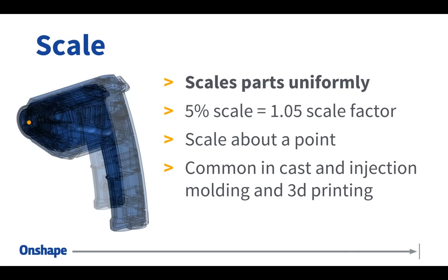It's also very common in 3D printing when you just want to simply scale something up, or if you've brought in geometry that needs to be scaled to a certain amount. Again, working with imported models. But think of any scenario where you need to adjust the entire scale of the entire part in one shot. The example I like to give is, I'm designing this power drill, and the power drill is an injection molded part. And when I'm designing the mold, I need to scale up by a certain amount to factor in that shrinkage that happens in the mold making process.